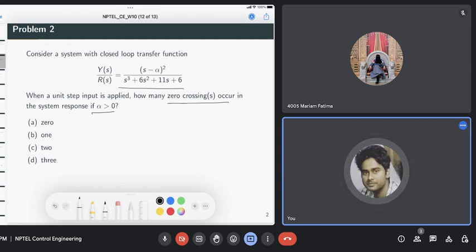provided the closed loop poles of the system are asymptotically stable, right? The closed loop poles will be located in the left hand plane. So first we have to verify whether this closed loop system has the poles in the left hand plane. So there are two ways to verify. One will be just factorization of this term, so we can simply factorize this.